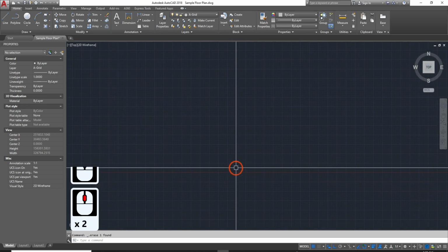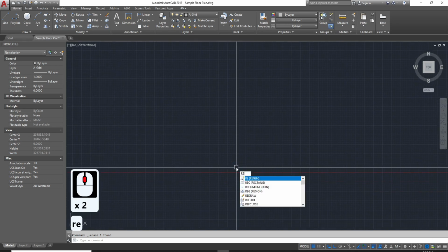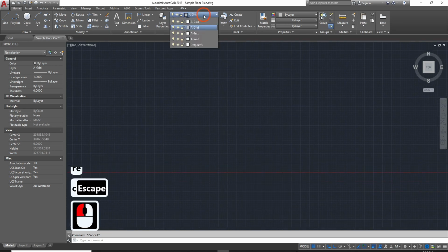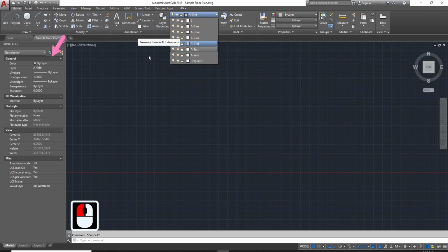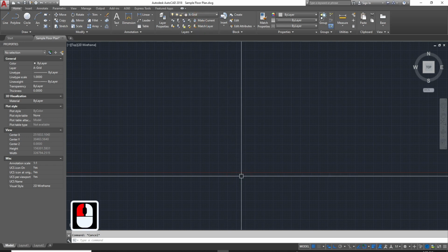Before I forget, I made a new layer called Grid and set it to current. My purpose is, we'll put all grid lines in this layer. You do not have to follow this. You may create your own layer system as you get familiar. But you get the point. Organize your lines, text, blocks, and dimensions. If you have time, Google the standard CAD layer naming.